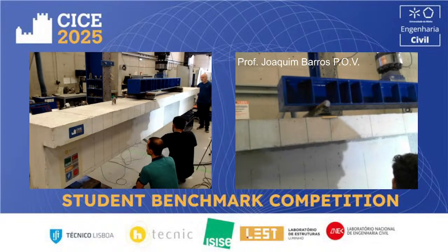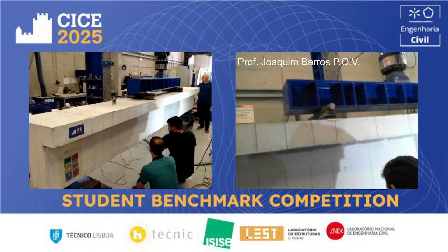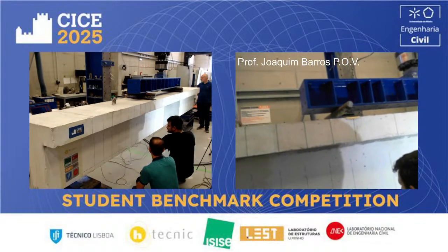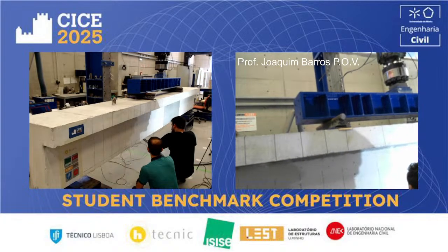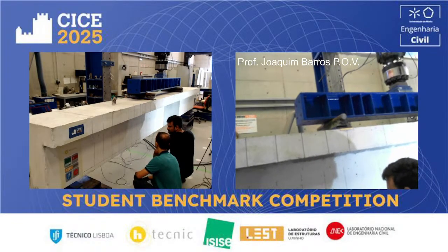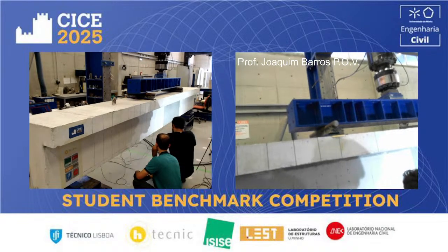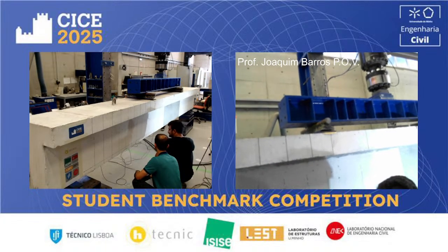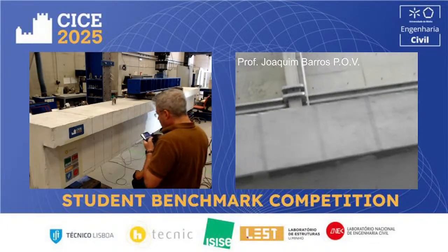In this stage, the response between the load and the deflection of the beam is linear elastic. Then after crack initiation, as you know, the stiffness will decrease due to the crack propagation. And then at a certain moment, we will have another decrease in stiffness when the flexural reinforcement starts yielding.